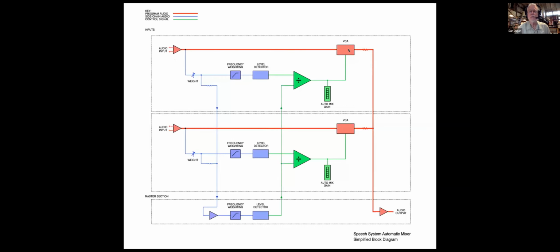You can see again, the red is the audio signal, and that's a very simple path. There's only a VCA, so there's no echo cancellation or all these complicated calculations that are done on it. It can be very simply done in analog. And then you have the side chain in blue, and you get the ratio between the level of the signal in the channel to the sum of the signal in all the channels. Now, if these things are logarithmic, then that's simply a subtraction. You're simply subtracting those two things. So it was very simple analog computing.